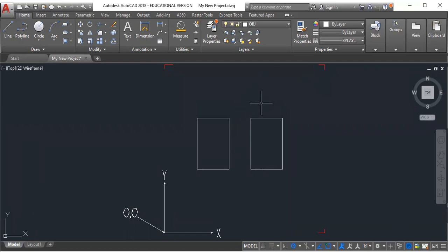Here's the important thing that I want you to see in this. We've got 2 ways to draw a rectangle, and trust me, there are others. But right now, we're just going to stick with either the around the block method or the method of using the rectangle command. Here's the difference. As I roll over this rectangle, let's say I wanted to modify it somehow. Let's say I need to modify by erasing this line, the line here on the right. On this one, I can just choose the erase command, come to this one, and erase that line on the right. Very simple.